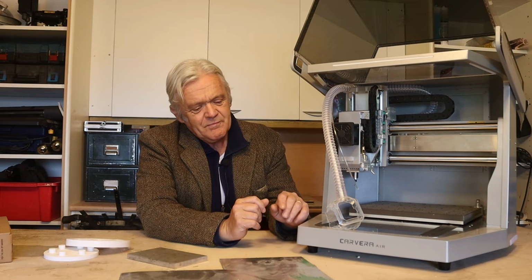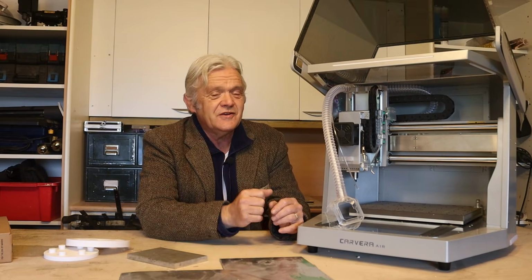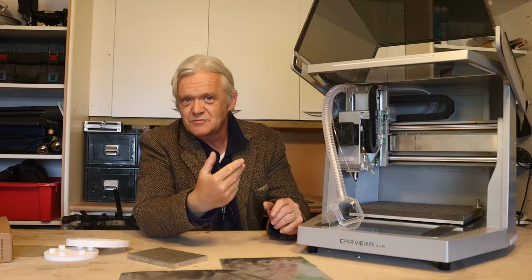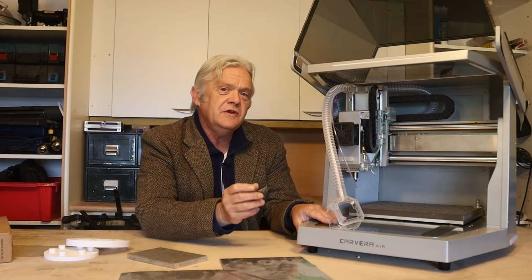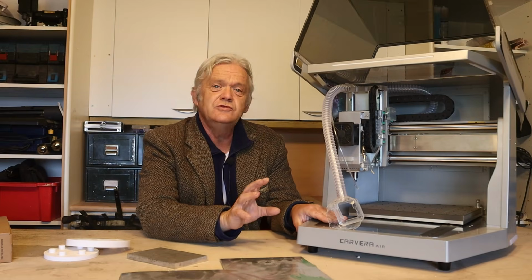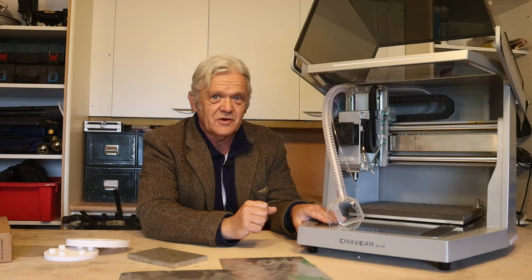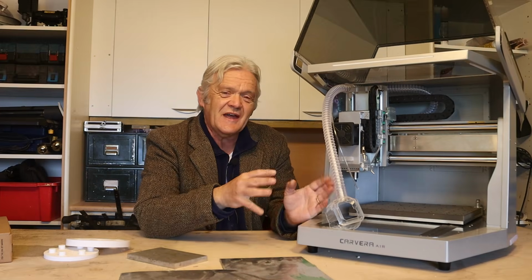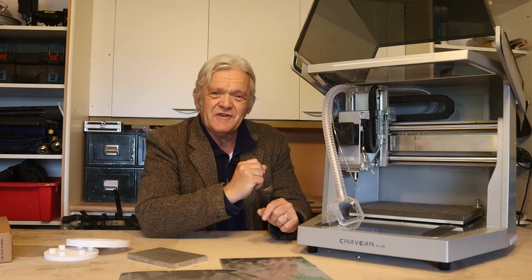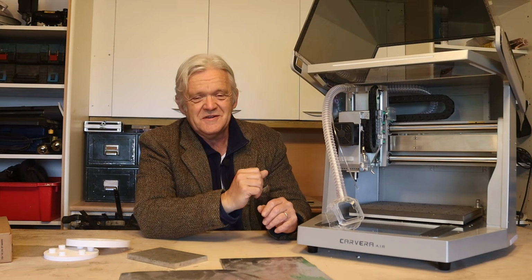And unfortunately, even though there is a standard defining G-code, there are always tiny little differences between controller boards and machines as the manufacturer makes them. And so they release profiles, and quite often you need to add that profile into whatever CAM software you're going to use in a process called post-processing. It takes the standard and makes it specific for the machine, which is a bit inconvenient if you think about it.